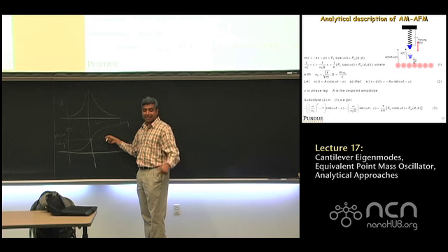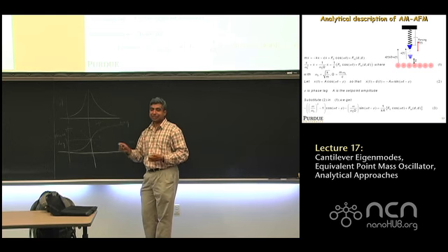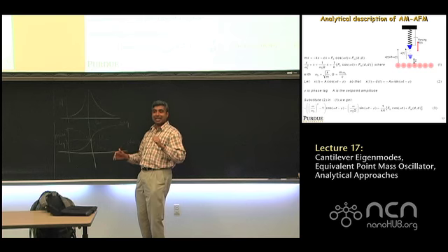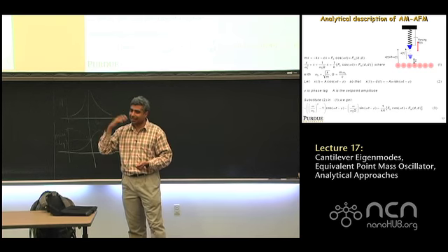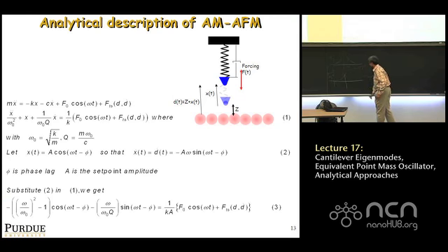If it's phase lead, you would call this minus 90 degrees, because at resonance, the oscillator is lagging behind by 90 degrees. So if you're plotting lead, it'll be negative 90 degrees. Okay? See what I'm saying? That's why lag is nice, because lag is always a positive number. Okay, so you do have to center it just to make sure everything makes sense.